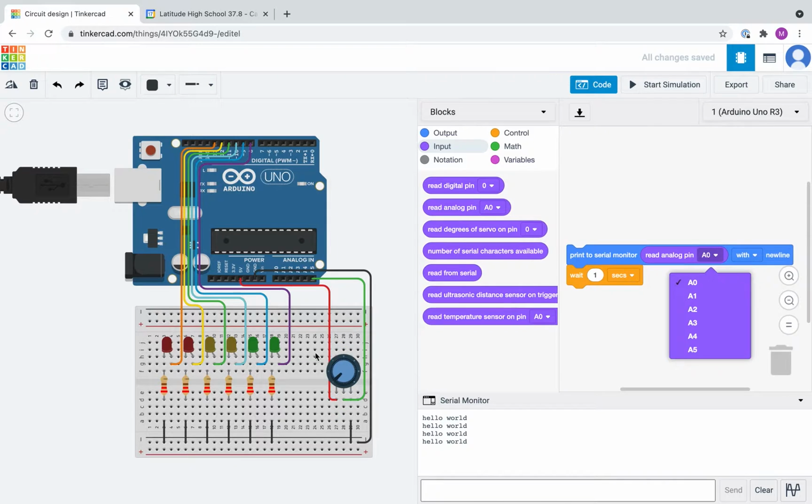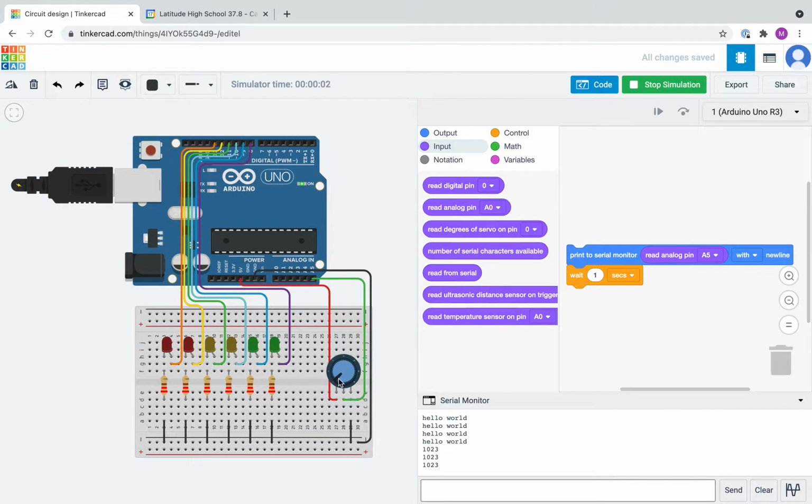and this potentiometer is hooked up to 5 volts into ground, and then additionally we measure from the dial exactly what we are getting. And if you want to, you can Google this component, potentiometer, and you'll find some good documentation on exactly how to use this. But what I want to do now is just show you exactly what this will read. So I can start this simulation, and we start out with this reading of 1023. That's our maximum, but then if I dial that down, I can get all the way down to 0.